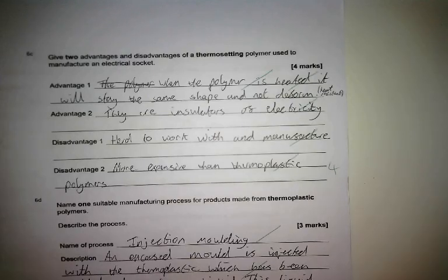We look at disadvantages then. Brittle, it tends to be very brittle, so plug sockets can break quite easily. Can't be reheated to soften, shape or mould it. Can't be recycled, therefore the waste goes to landfill, or the object goes to landfill at the end of its life cycle. Pollution from manufacturing process and material production. It's made from fossil fuels. At the end of the day, it's a plastic. We can't recycle it, so it's not going to be recycled plastic like a lot of thermoplastics can be, or the bioplastics we tend to get now as well. Anything along those lines. It doesn't have to be word for word like that.